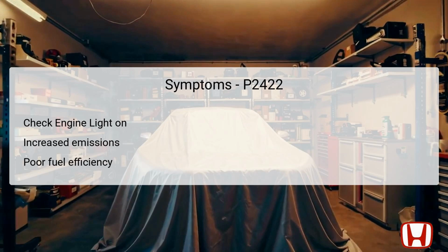Another common symptom is reduced fuel efficiency. The engine may not be able to optimize fuel usage properly if vapors are trapped in the system. Drivers may also notice changes in engine performance, particularly if the vapor recovery systems are not functioning effectively. Recognizing these symptoms early can greatly aid in timely diagnosis and repair.